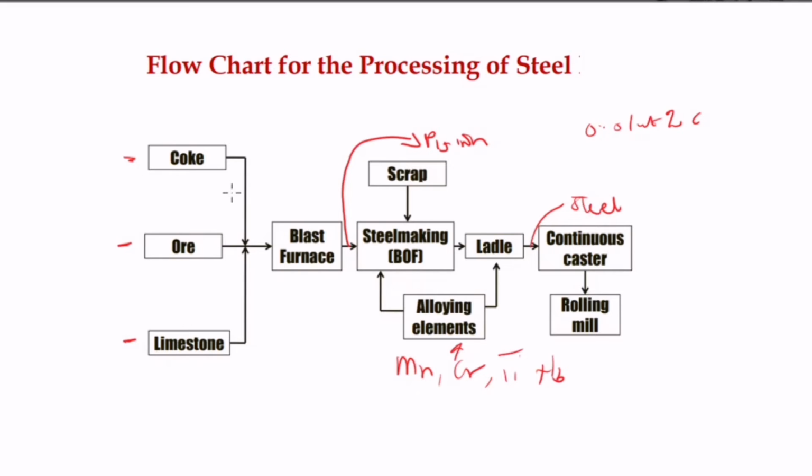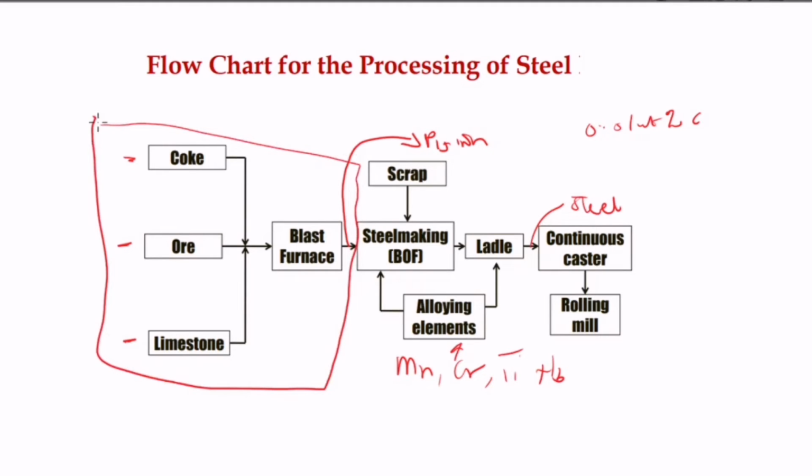So this is the flow sheet for this video. Our most important thing is to end at the pig iron here. So coke and limestone, which is a flux, are added to the blast furnace, and reactions take place. At the end we get two molten products, a molten metal and a slag, and then we get pig iron as a molten metal with a high amount of carbon.